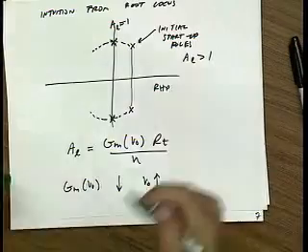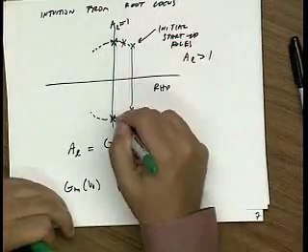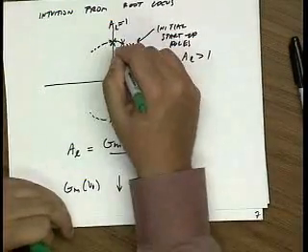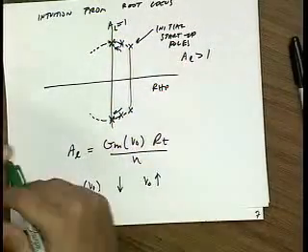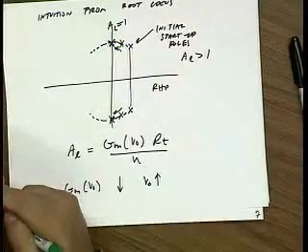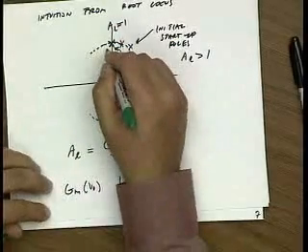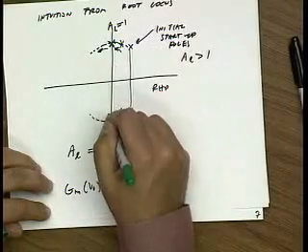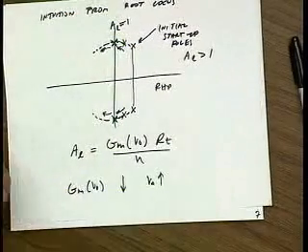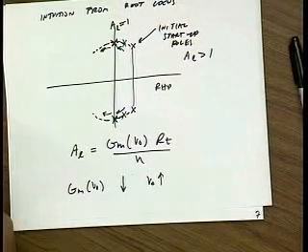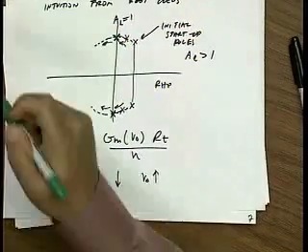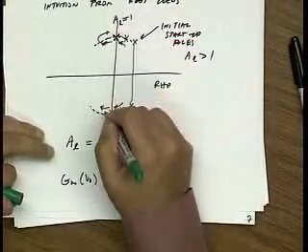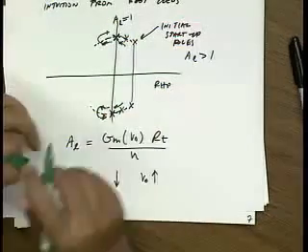Well, that we already discussed. So if somehow the poles move to the right half plane, there's a tendency for them to move back, because the amplitude gets bigger, the gain drops, and then they move back. Equally, you could ask, what happens if somehow they move into the left half plane? That would cause the amplitude of oscillation to decay. And as the amplitude of oscillation decays, the GM gets bigger, and that tends to push the poles back onto the j omega axis.